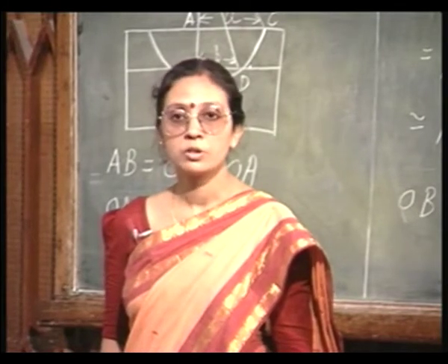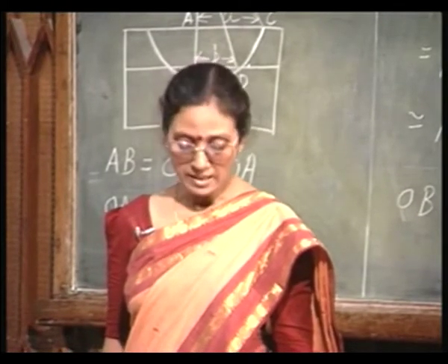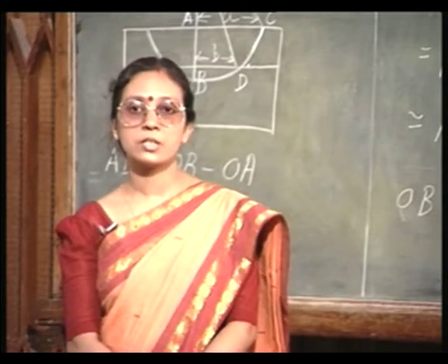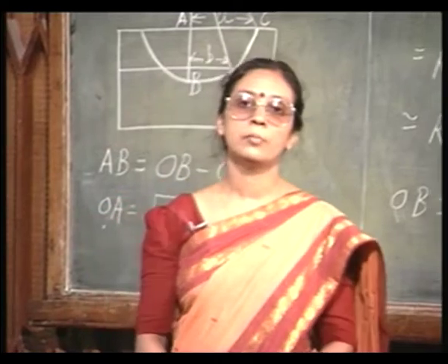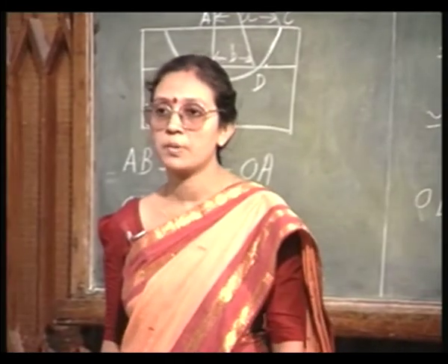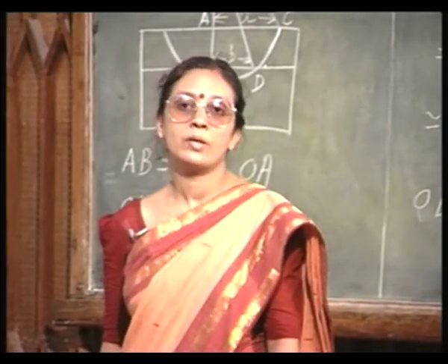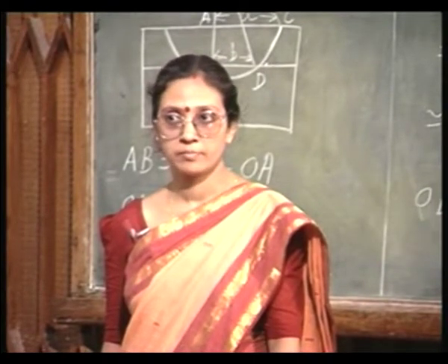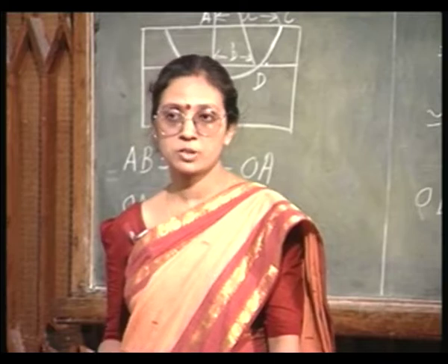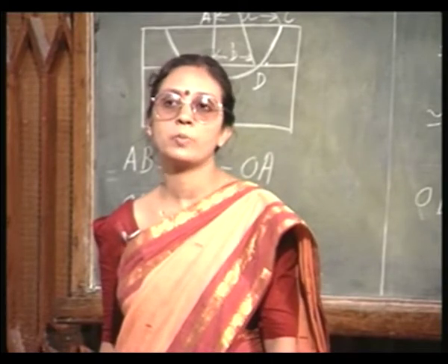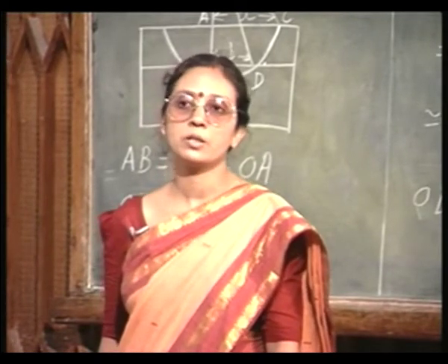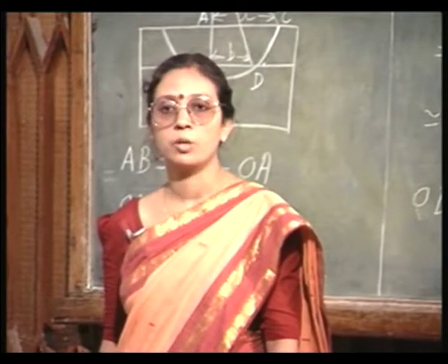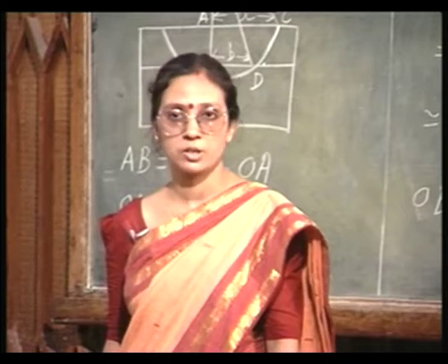You can count the number of fringes and that will be related to the junction depth. So, it is actually given as a function of the number of the dull fringes multiplied by the wavelength of the monochromatic light. Since you know the wavelength, you can find out what the junction depth is going to be. So, these three are the three most common techniques of measuring the junction depth.